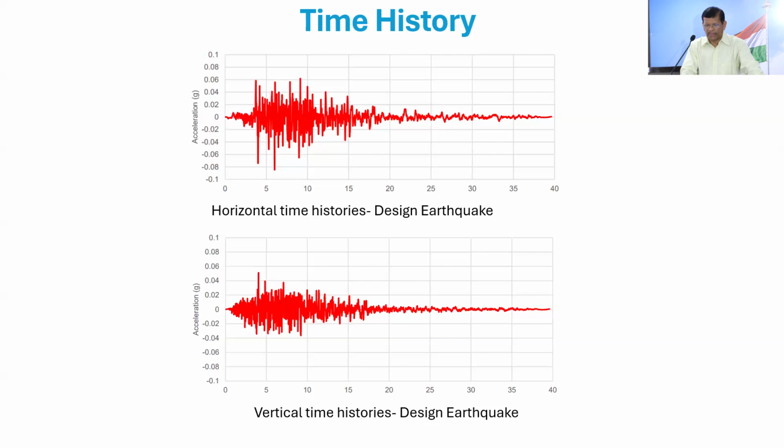design earthquakes, because in each time history you see the acceleration and how it is changing with time, and mostly the duration is 20 seconds, maximum is 20 seconds. It all happens during 20 seconds. Sometimes we see that the PGA value is lower in that model, but the shaking continues for more than 20 seconds. So that's why in the initial phase we go with 3 or 4 and then identify our critical one. Then further development we do using that critical one.